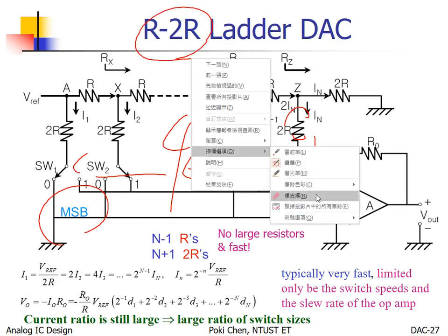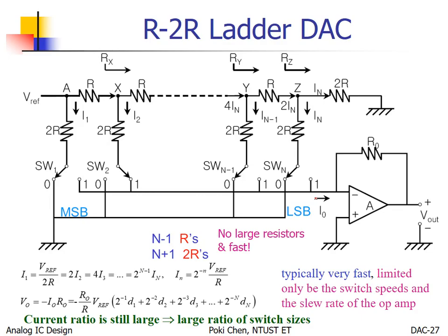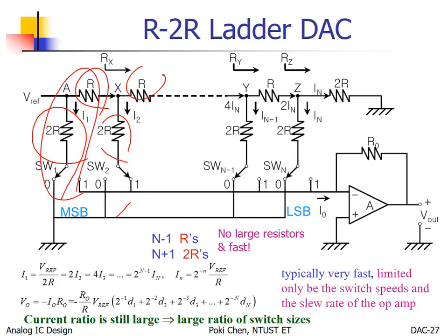So, with such a very simple structure, for each bit, you have one 2R and the other 1R. That is for MSB. And next bit, 2R and 1R. Every bit 2R and 1R, 2R and 1R, that's it. Only for the final one, you have a dummy 2R. That's it. Okay? All right, bingo. Oh, congratulations. But what is the problem?